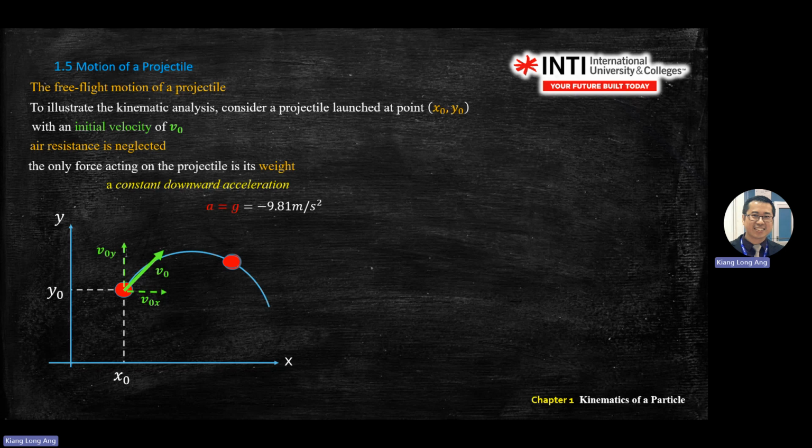Okay, again, by fixing your axis, x is positive going right, going up is positive, y is positive. So when your vector of acceleration is go down, your magnitude of the vector will be negative. If you put positive, when you draw your axis already, and all the value when it become positive, means it follow all the axis direction. So this is the careless mistakes. So remember, in engineering dynamics, always follow the general axis that you draw.